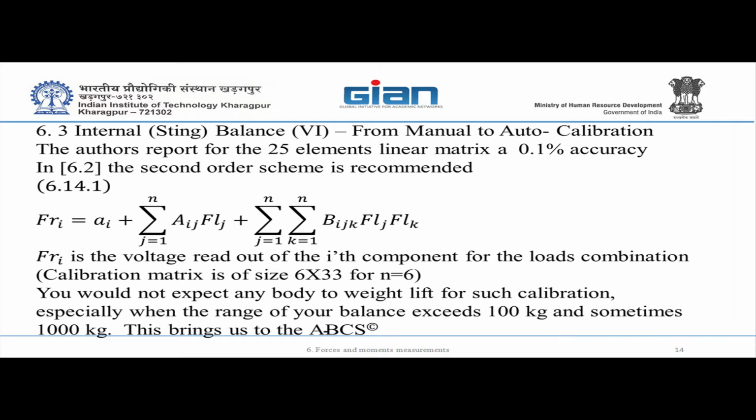So suppose the maximum load coming in is, say, 50 kg, and my load cell capacity is, say, 2000 kg or 5000 kg. Then that's a problem. That is a problem with the test. It's not a problem with the machine. It's a problem with the test because you didn't pick the right balance. Suppose, say, before testing, I don't know what the load will be.